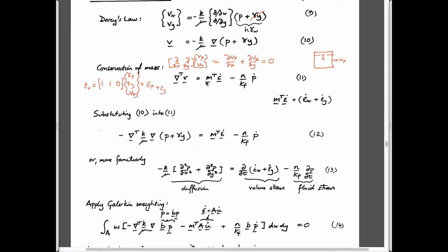So that's what this term is. If you change these to rates, then you can do that just as easily. Physically it's just conservation. If you squeeze it, you change the size of it by straining it, then that certain amount of volume has to come out, and there's no change in fluid pressure that occurs with that. So displacement changes, but the other dependent variable doesn't change because there's no fluid pressure change.